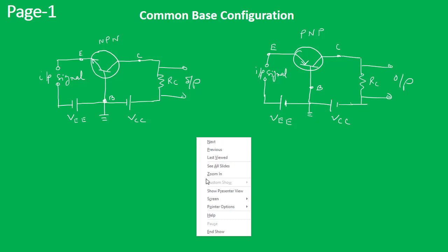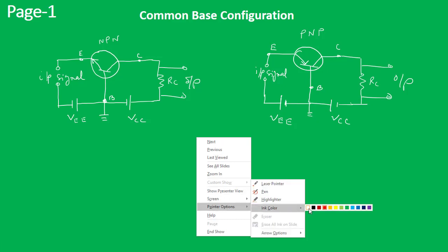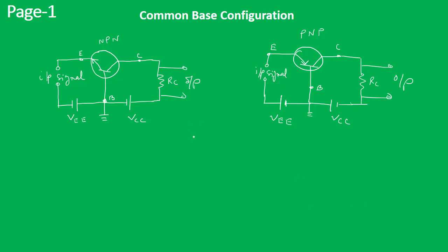In our previous lectures, we have discussed this, and here it is shown that for NPN and PNP transistor, how transistor can be used in a circuit with the proper biasing. So now in our previous lecture we have seen that the base emitter junction JE is in the forward bias, whereas the collector base junction JC works in the reverse bias.